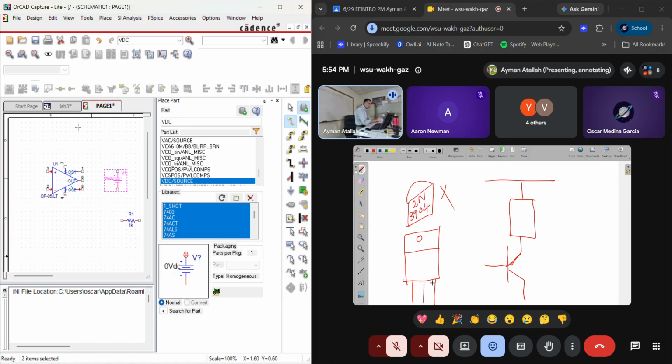So I'm going to get the current from the operational amplifier, the current that will open and close the transistor, which is like a switch here. The motor will get the power from the power supply itself, and this is ground here.